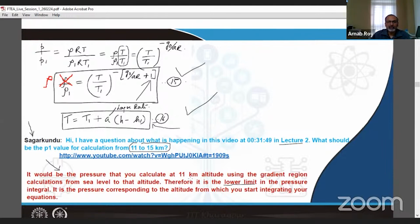Whatever you get at 11 kilometers altitude basically takes up the 1 level. And then you move on in the isothermal region between 11 to 15 to perform your calculations, starting with those subscript 1 levels. So that's the idea. Now, let's try to move on from here.